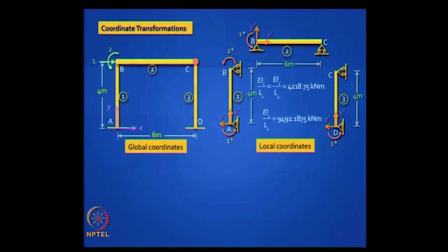we knock off the rotational degree of freedom at C. So the size of your stiffness matrix, your TD matrix, reduces. You have 2 degrees of freedom for element 1, no change there, and you have only 1 degree of freedom for elements 2 and 3, and you should release at the right place where there is the moment release, there is the hinge, internal hinge at C. It matters little whether the hinge is internal or at a support. Clear? Okay. How will this change?